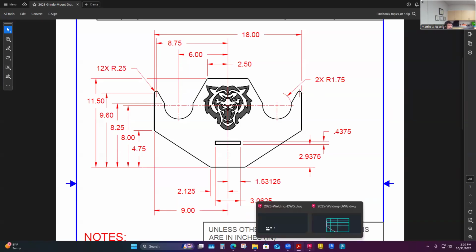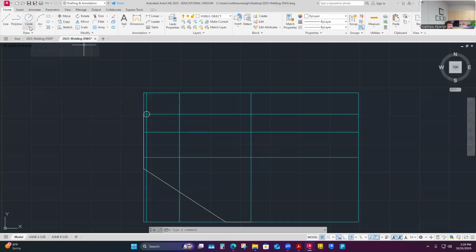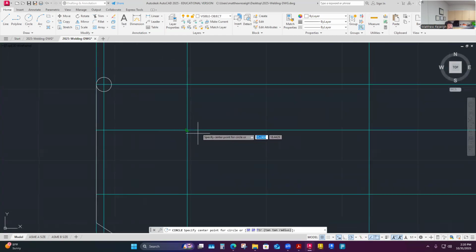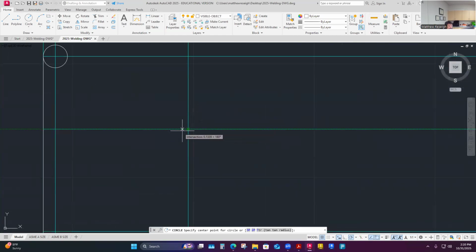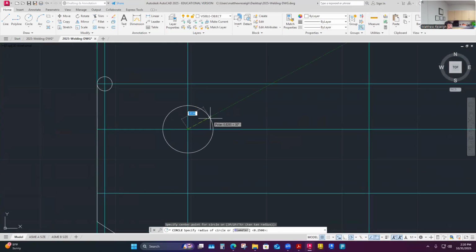Let's draw that in. So here's my circle command, circle radius, what I want. Here's the center of the circle, so I just hover over it. It's picking up an intersection point or even a perpendicular grip. Either one is going to be okay. I'm just going to snap it. That's a left click and then pull out.